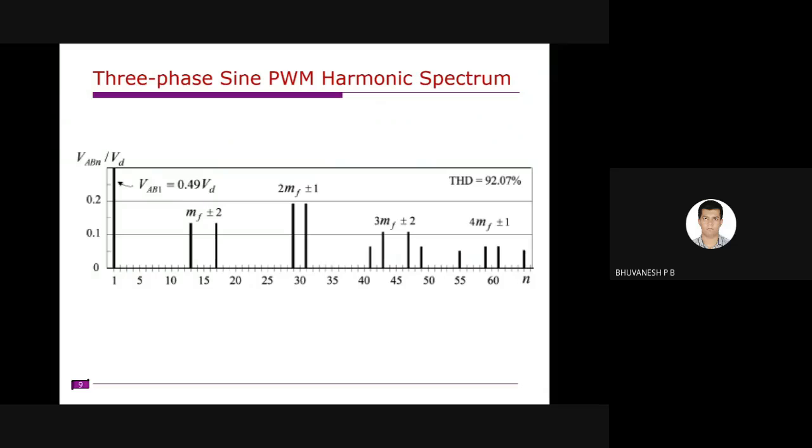Yeah, this is the corresponding harmonic spectrum, considering MF equal to 15. Here you have no harmonic at MF, 2MF, 3MF, or any MF.